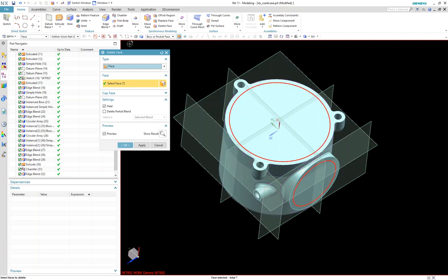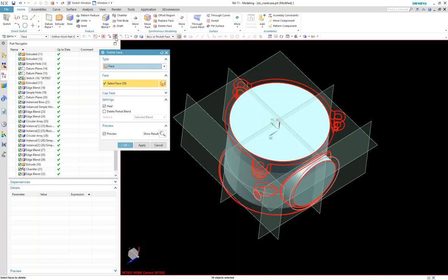So the next thing we need to do is come over to the top border bar here, and you can see we have those new options that were added, the All But Selected and the Select All. For this case, we're going to do All But Selected. This is going to deselect all the currently selected objects and select all the other selectable objects for the user automatically. So I'm going to go ahead and pick that, and you can see my graphics window has updated. Now all the other faces on the outside of the body have been selected, and it's going to delete those faces off of my model.